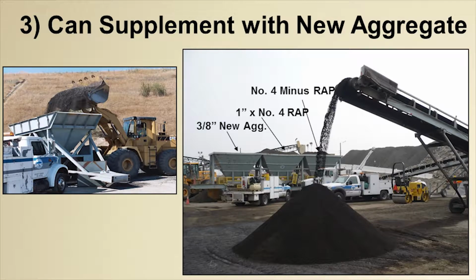So cold in place recycling is an excellent process and is used all over the country. We do a lot in California. We do 15 projects a year, probably just for the state of California. It's kind of funny when people talk about low volume roads. In California, our low volume road is typically 30,000 ADT for the highways. I would love to put 4 inches of HMA on top of it, but we typically recycle 3 inches and put in a 0.10 HMA cap on those type of roads all the time.